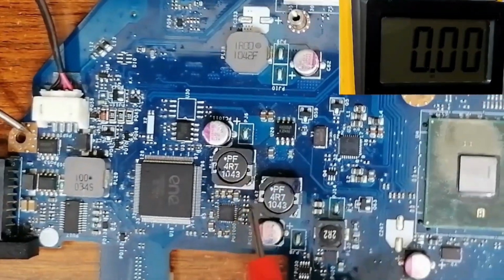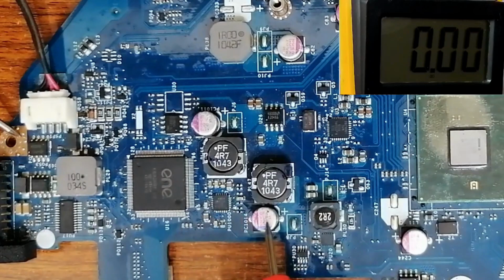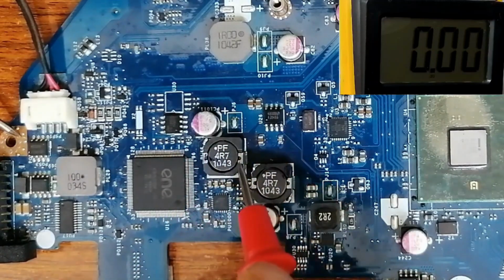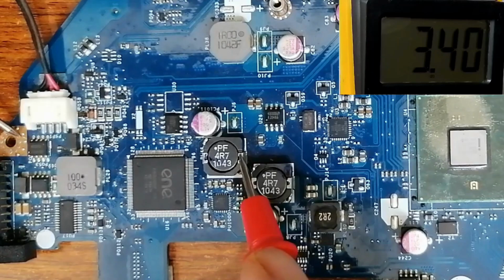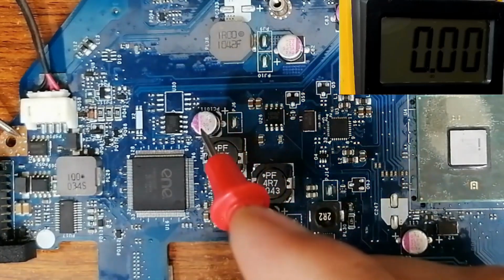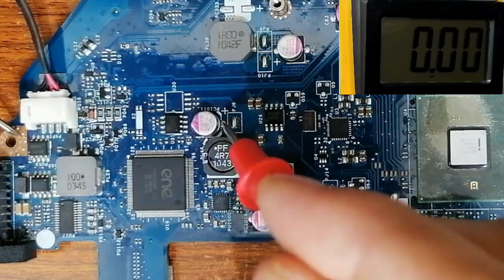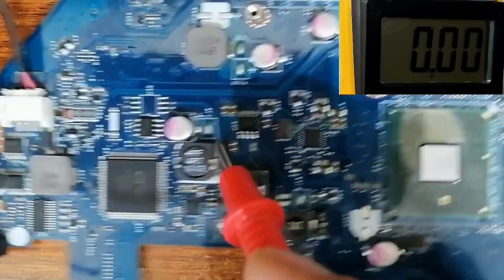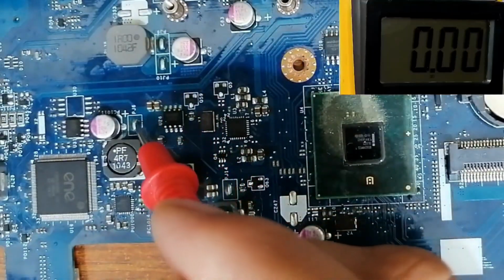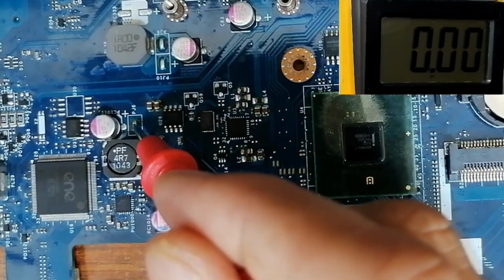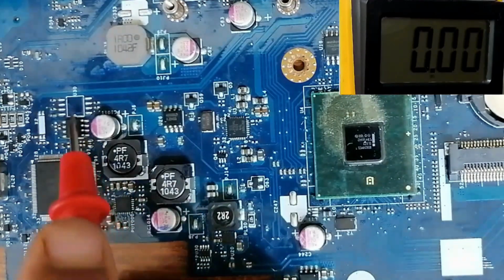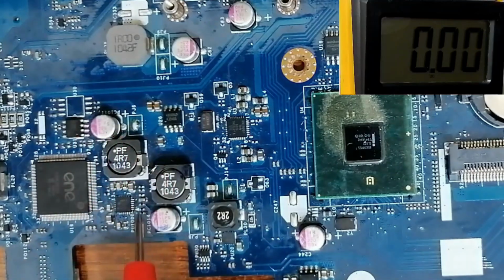So for 3 volt 5 volt circuit, you're gonna find always two channels. The first channel for 5 volt and the second channel for 3.3 volt. So you can take measurement here in the inductor, we have 3.3 volt, or in the electrolytic capacitor exactly in the positive terminal. As you can see, we have 3.3 volt, or here in the test point. Do you see this? This is pad or test point. Let's check. We have 3.3 volt. So this is 3.3 volt channel. And this is 5 volt channel.